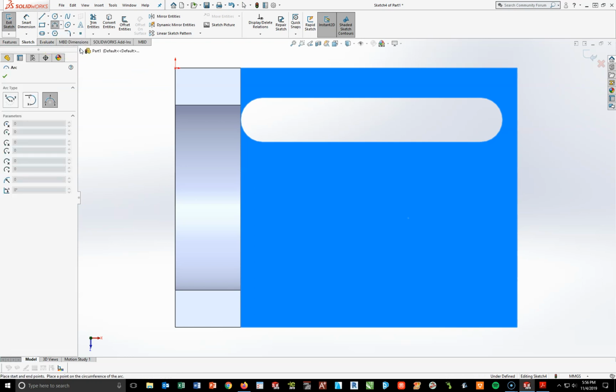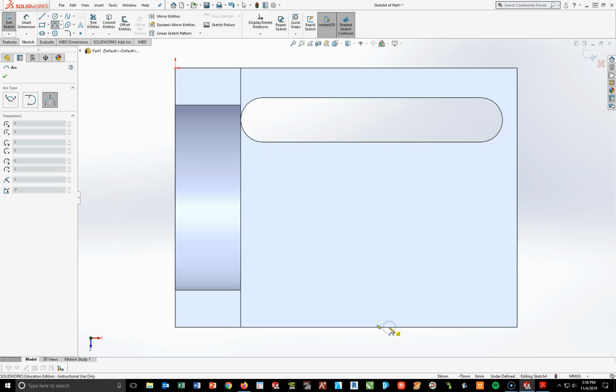Now if you recall, we talked about this in the beginning of doing SOLIDWORKS. If it says 3-point, it means 3 clicks of the mouse. So I'm going to start down here on this edge here. I don't want to get locked in this midpoint because that's not where this belongs. I'm going to be a little bit in front of it. I'm going to left click, number 1, come this way so it's kind of towards the middle, left click number 2. Then I'm going to pull a shallow arc right here, something right about like this, left click number 3.